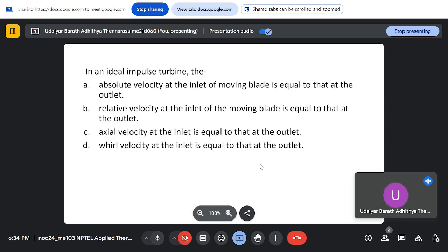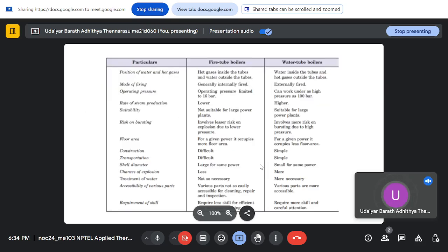So with that, the condenser part is mostly similar. If you have a water-cooled system to condense the steam, or you can basically use what are called cooling towers, which are generally used to condense the steam. You pour the water from the top and pass air, so some part of the water gets evaporated and the water condenses. That energy is taken away from the water itself and the water basically cools. So that is the principle of a cooling tower.